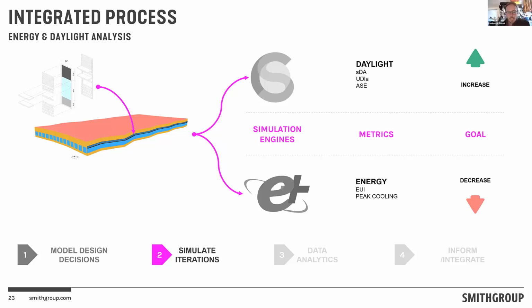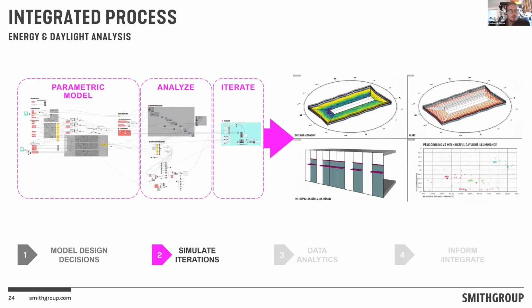On the next slide, you'll see a parametric workflow. So we're using Grasshopper, a visual scripting interface for Rhino, to build our geometry on the far left, first box. In the middle is our analysis engine. So there we're running it through ClimateStudio and EnergyPlus. And we're using Colibri on the far right to iterate through all those combinations and record the data. So the graphic that you see on the right here, behind the scenes is full-scale, annual daylighting analysis, as well as energy analysis for each of these different options.